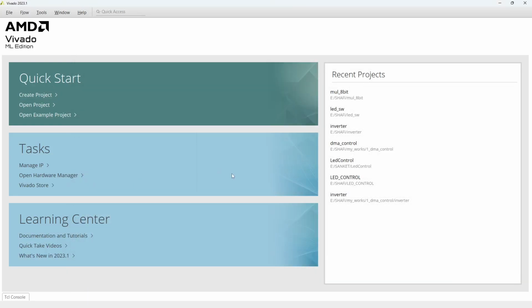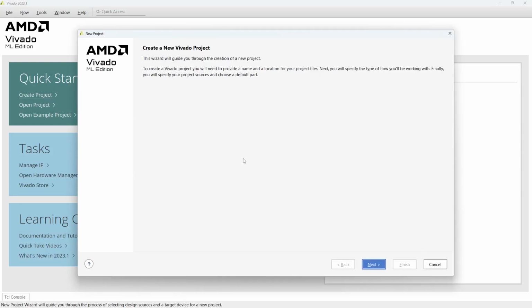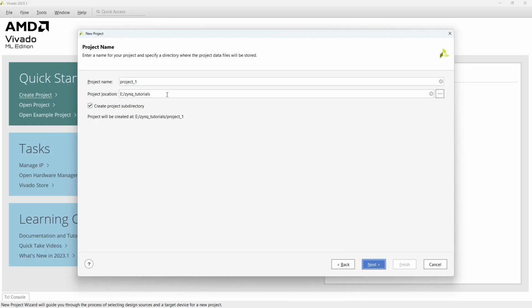I will just explain my complete intention. I will create a hardware that can do image inversion. That is my target. So we'll start with a particular IP that can perform that task. Then later we will create a block design in which we will use this customized IP, and where we'll write the Vitis code to feed some input and check whether we are getting the negative or not.